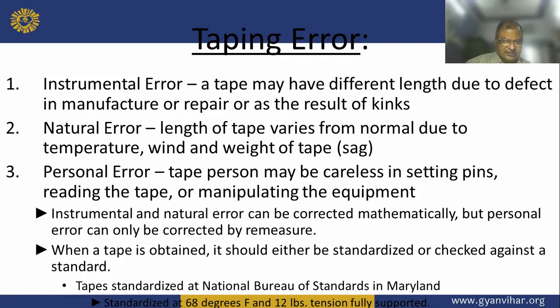Natural error: the length of the tape varies from normal due to temperature, wind and weight of the tape. Personal error: the tapeman may be careless in setting points. Instrumental and personal errors are corrected mathematically.